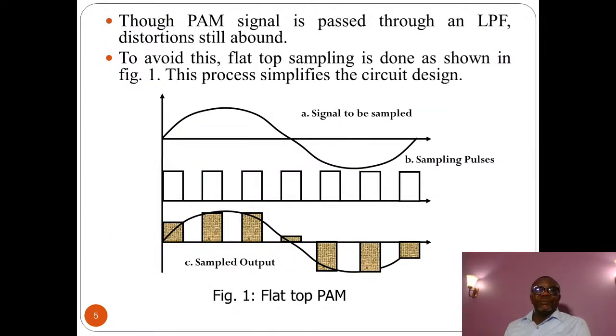Though the PAM signal is passed through an LPF, low-pass filter, distortions still abound. To avoid this distortion, flat top sampling is done as shown in Fig 1. This process simplifies the circuit design.